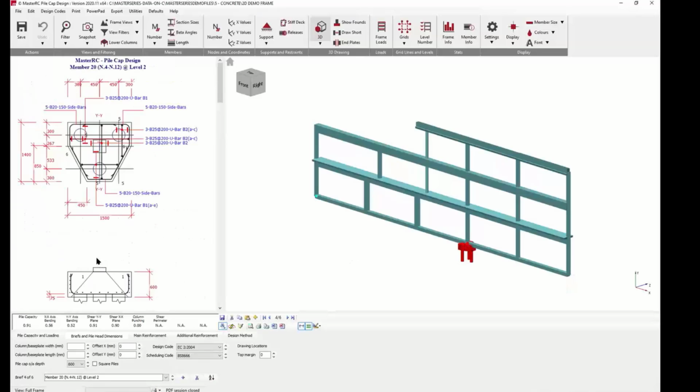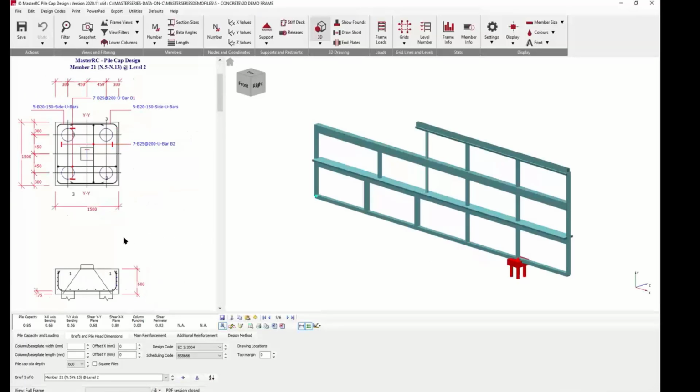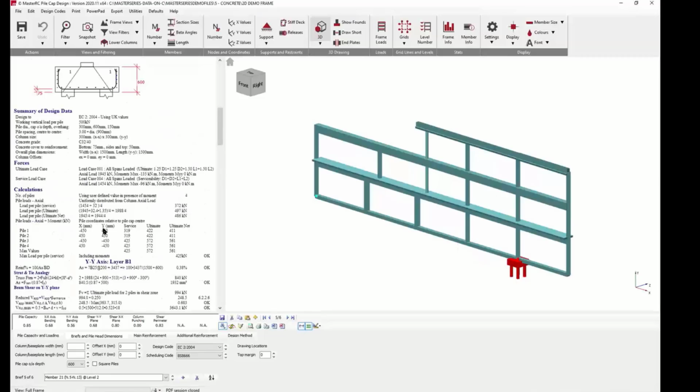And if I look at my 4, you'll see again it's looking at different loading, and it's looking at different loading in the major and minor. The minor, it's the same, but the major, it's got this moment of 96 to consider and handle, and moment of 135 at ultimate limit state to handle. So it is working away and doing everything you need.